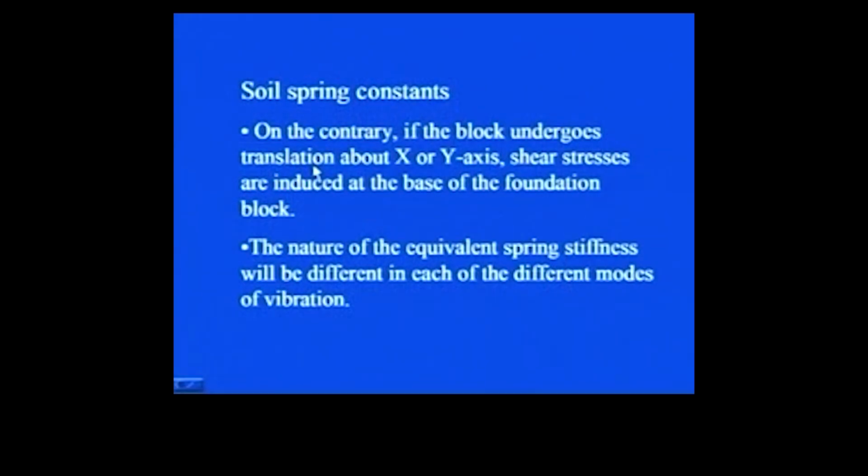In one case, compression at the base of the footing is induced, and in the other case, when the block is undergoing translation about the x and y axes, shear stresses are induced at the base of the foundation block. The nature of the equivalent spring stiffness will be different in each of the different modes of vibration.